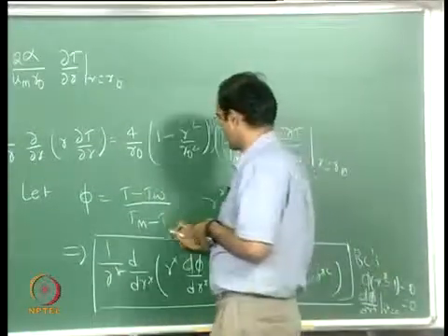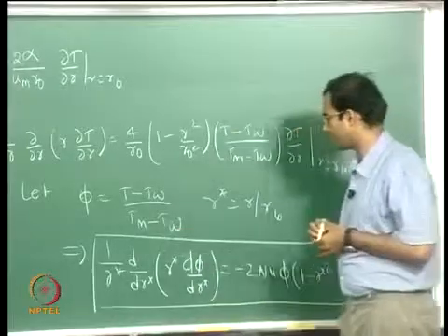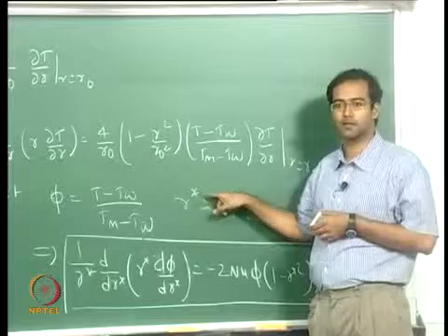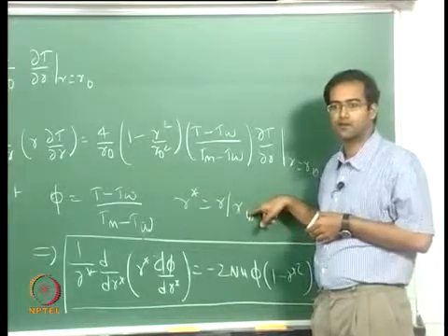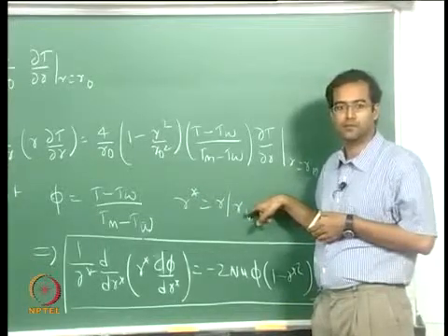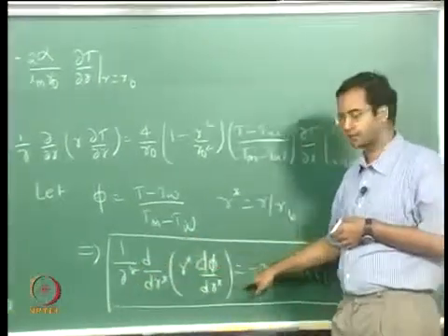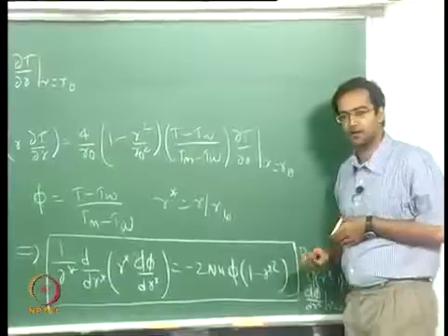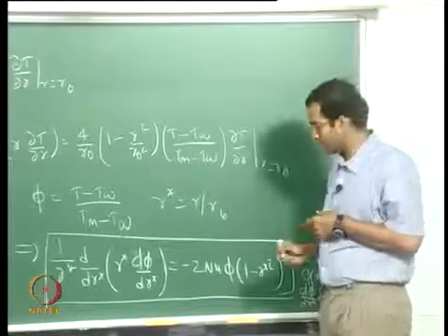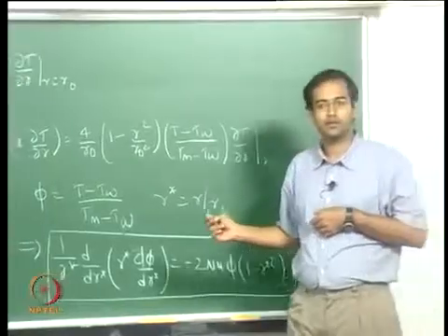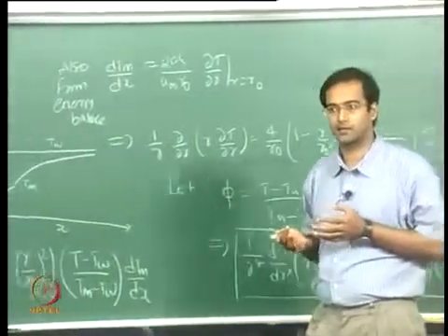Okay, so therefore I can non-dimensionalize my radial coordinate also. I can introduce a non-dimensional radial coordinate which is r by r naught, where r naught is the radius of the duct. So the final resulting expression, if I substitute that, will come out in the form that is presented here. This is nothing but an ODE which can be solved by the shooting method, once again iteratively.